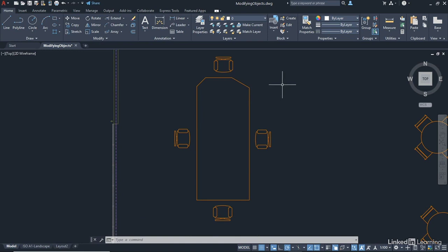So you can have different types of chamfers using the two different methods as well. So remember that when you're using chamfer, because you might want an irregular chamfer with a distance and an angle using the angle method, or you might want regular distances using the distance method. So you can see two different types of chamfers there using the chamfer command.